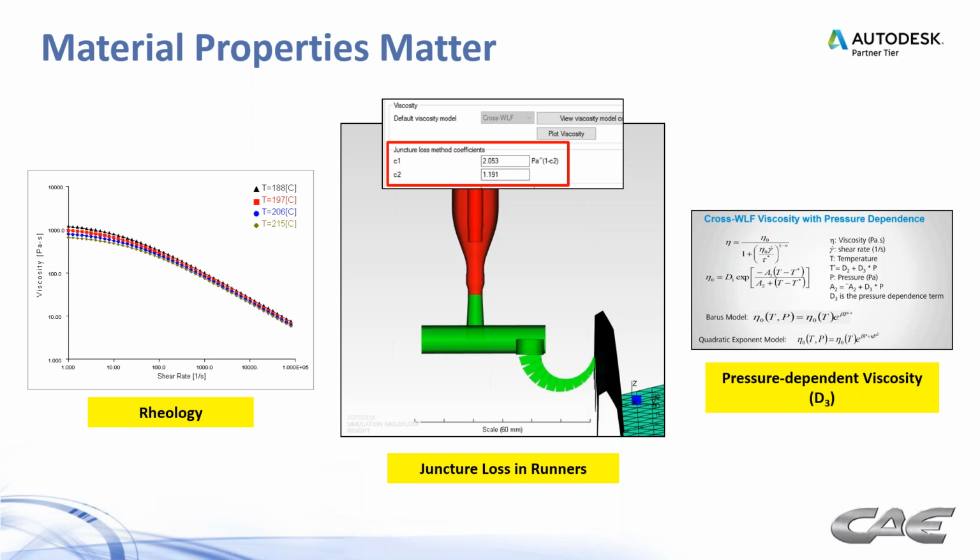And then lastly, this is not something that many materials in the Moldflow database actually are characterized for, but it's called pressure dependent viscosity. This gets into areas where very high pressure molding tends to exhibit this type of behavior, on polycarbonates, PC/ABS, very thin wall geometry, long flow lengths, high pressures, et cetera. So this can add to the pressure requirement as we get up into those higher pressure situations.